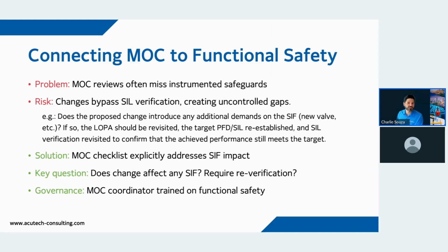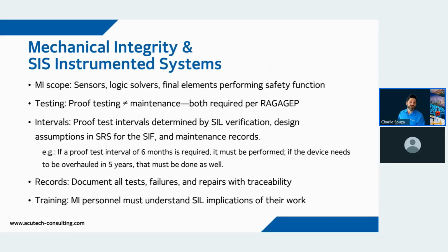And if that's not addressed, revisited, then it is not going to act on time to prevent an accident, right? So that would be the goal of this slide, is to show you that even small changes may affect your functional safety. You may say, well, but this MOC is not on my safety function. This MOC is on the BPCS, on the DCS. Yes, but now it is increasing the load or the speed requirement, the reaction time requirements of your safety system.